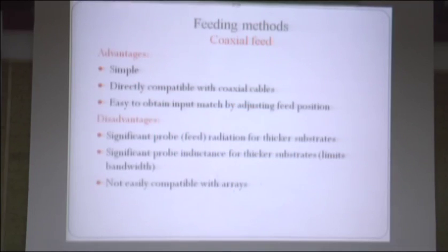Advantages of coaxial feed. It is simple, directly compatible with coaxial cables, and easy to obtain input match by adjusting the feed position. We can change the feed position and easily obtain an input match.